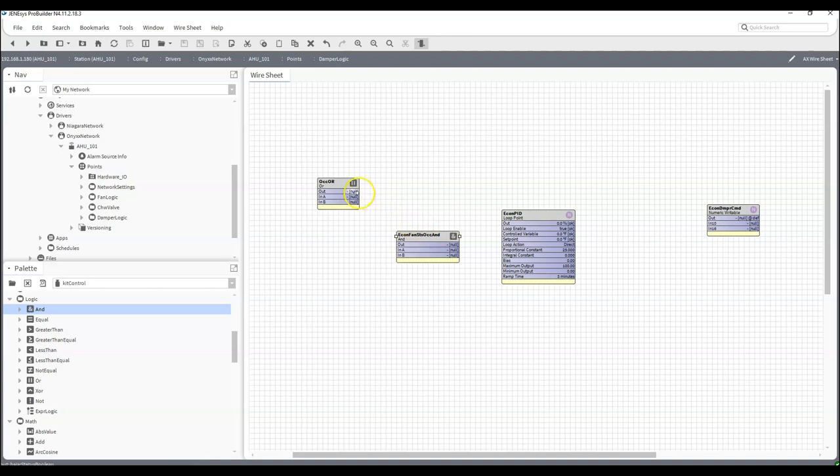And so I'm going to link my OR to my AND, and I need the fan status and the occupancy. So therefore, I'm going to pin out the slot here and go to NC. And then I'm going to enable my loop based upon that. Now I'm going to composite out my controlled variable and my set point as well. But a couple other things I need to do.